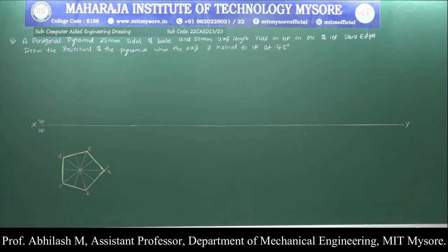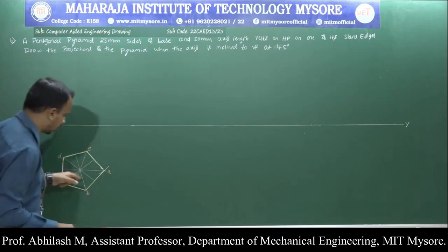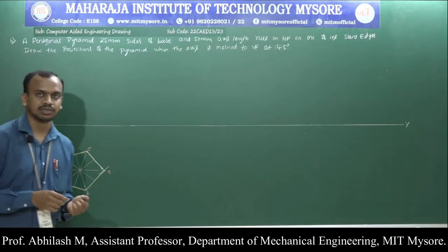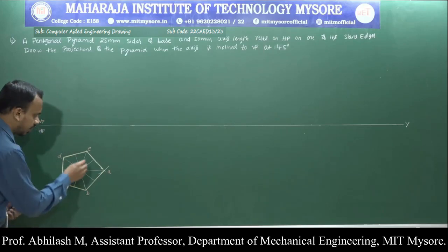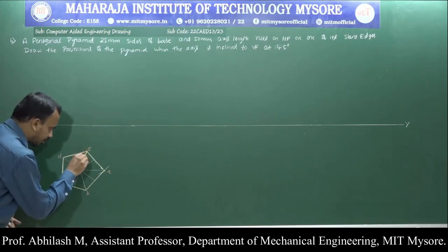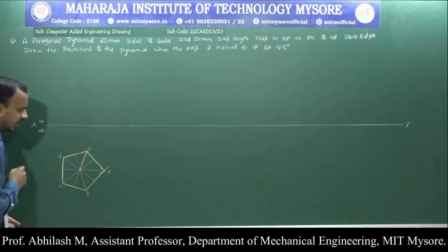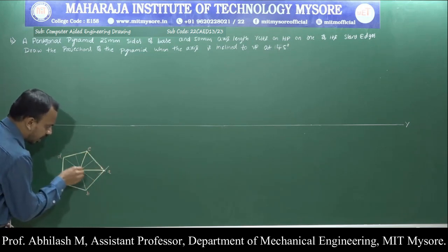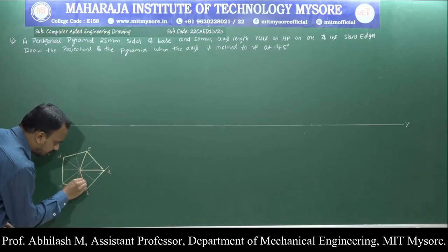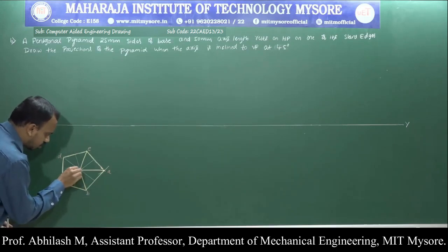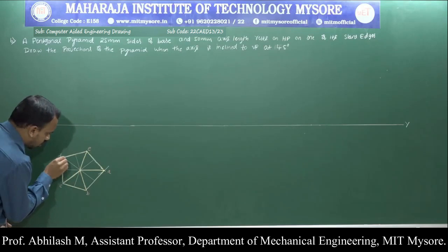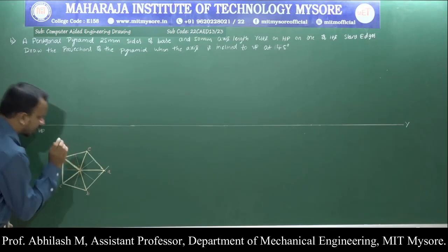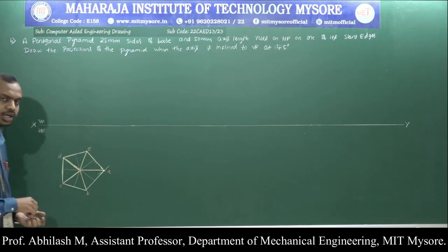So we have got the point where the axis is going to begin, or the point of the axis, but here the portions that are visible become very important. From E to O or O1 it is completely visible. From A to O, similarly from B to O, C to O, and from D to O. So these portions are completely visible from the top.